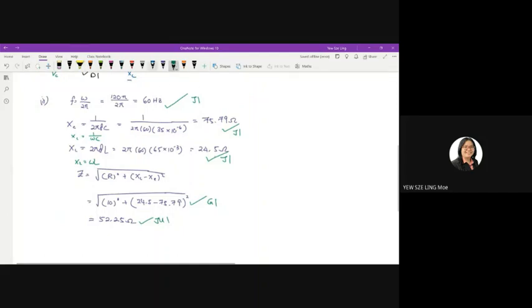You have a V maximum, question 4. Your V peak is equal to 156 volt. Now you want to calculate the RMS value. Of course, you need the RMS voltage. So VRMS is equal to V peak over square root 2. Plug in the value and you should get 110.31 volt. That is your VRMS.